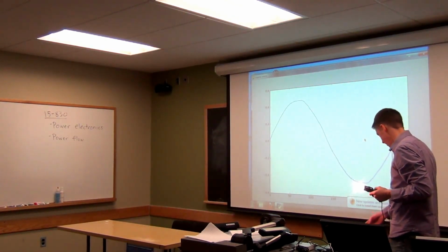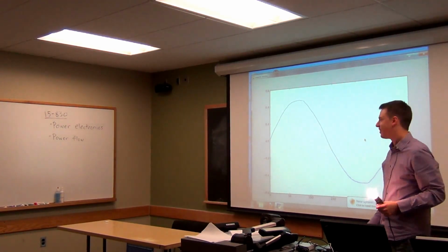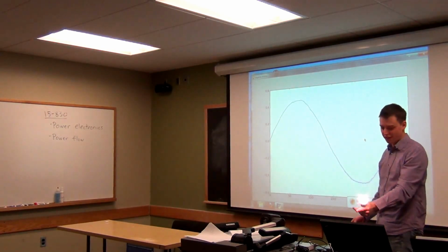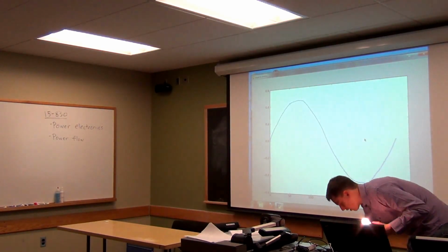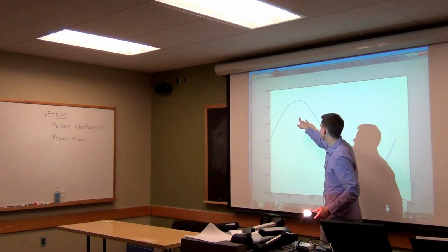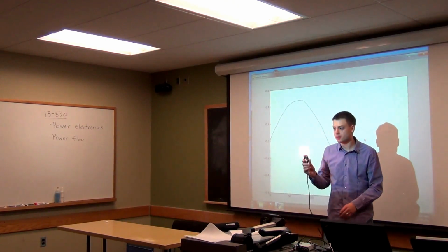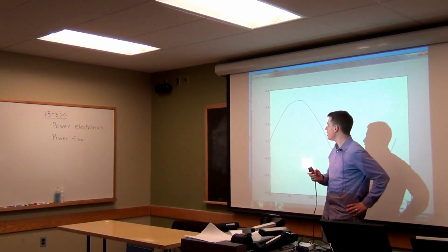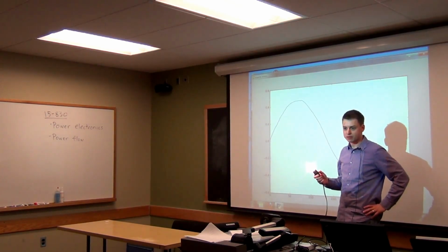There's a little bit of noise, especially might be caused by this whole chain of stuff that I have going here, more than the light bulb itself, or just actually noise in the actual sensor itself. That's actually probably the more likely thing. We're talking about relatively small amounts of current here. So this is 0.4 amps of current to power this light bulb. This light bulb is 40 watt, and so this makes about amount of sense, right?